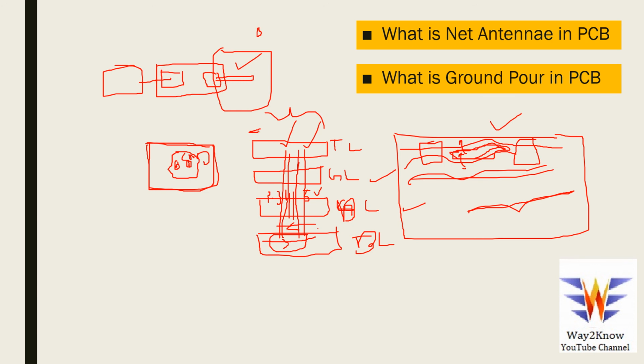You can leave it open because these are low frequency signals, and the radiating, or coupling to another trace because of the capacitive effect is very little. But if there is a high frequency signal, because of the capacitance between this pour and the trace, the signal gets coupled. So we have to be very careful, and we have to ground this using wires at some points.